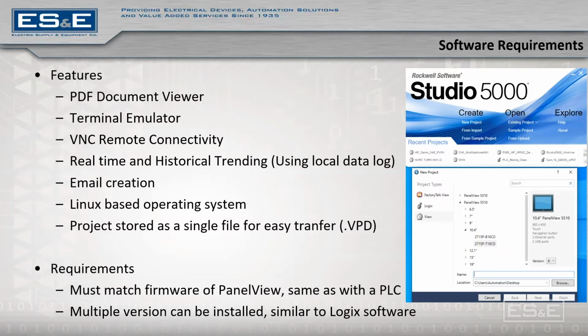The PanelViews also run an operating system that is Linux-based, so you don't have to worry about updates or IT people coming back later on and having an issue with the operating system running on some of these PanelViews. And one other key feature that they have changed is they stored an entire project in one single file, a .vpd, very similar to how a controller works. And if you're used to PanelView Plus, then you are used to having a full folder structure in which you can only transfer the runtime and certain things like that. So they have tried to make this a lot easier on this new platform.